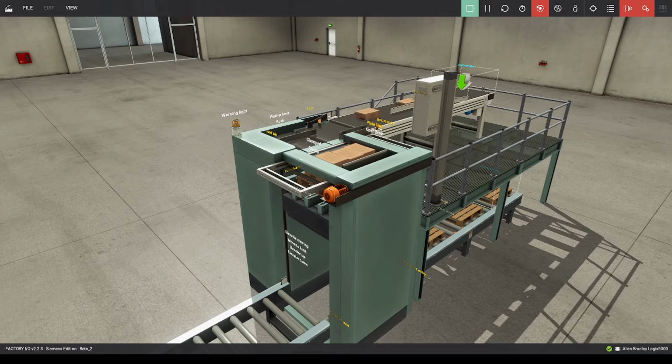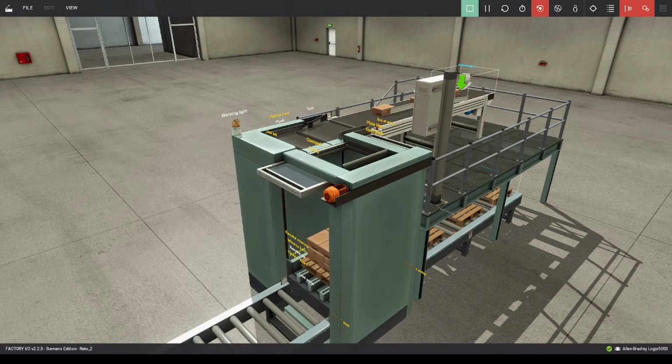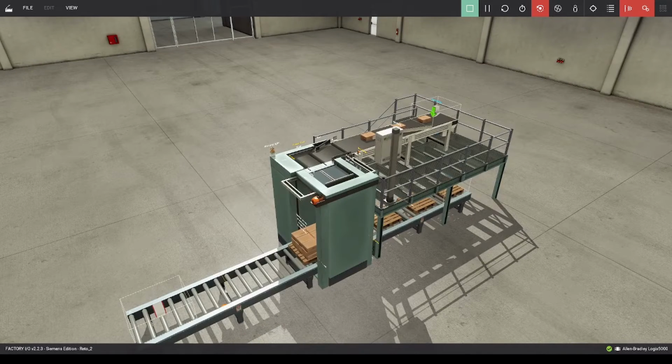Both configurations are possible with the help of an actuator that does the turning in each iteration if necessary. Once the pallet is full, it clamps the boxes and the plate opens, creating a layer. The process repeats with alternating configuration layers until the pallet is complete with 3 layers. Once this is accomplished, the elevator goes down and the filled pallet goes to the end of the down conveyor array to the exit, and the process repeats itself.